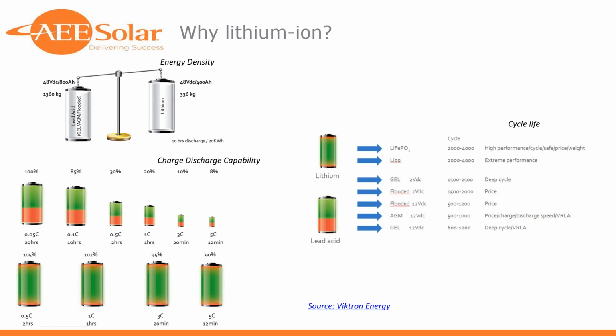The other point is that due to discharge capability and depth of discharge, on a lithium ion pack, you're going to be able to discharge 90+% regularly without harming the battery. That was the intended use case, the chemistries that were designed for that.